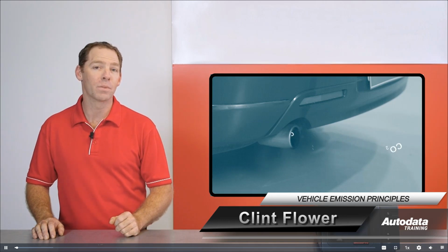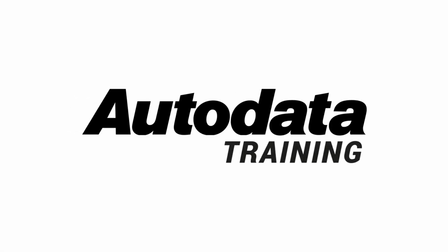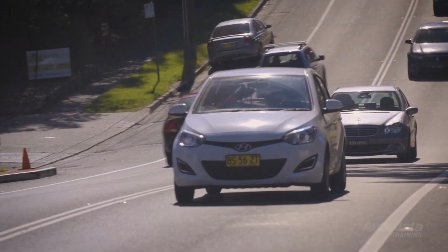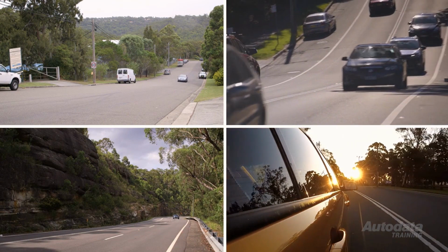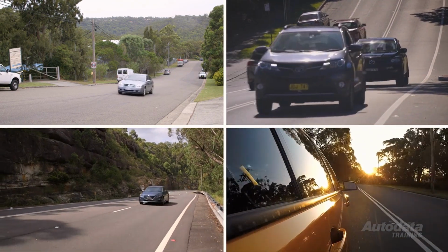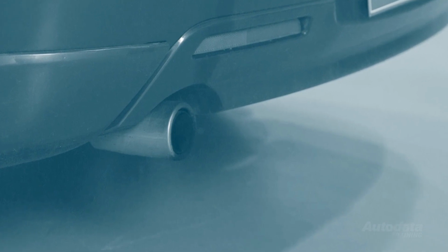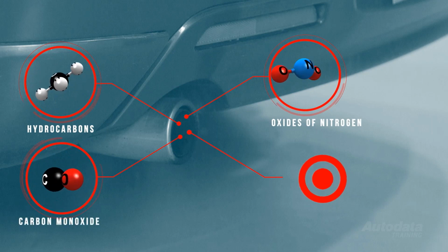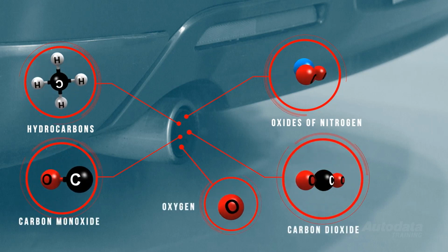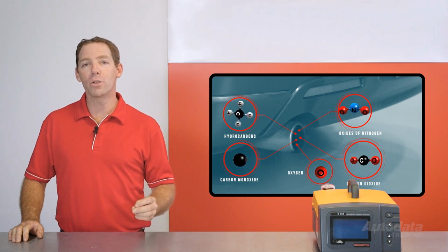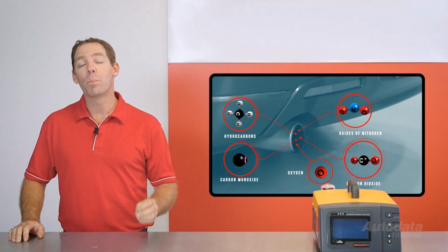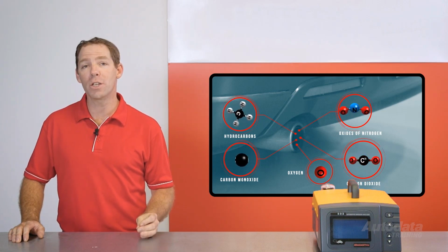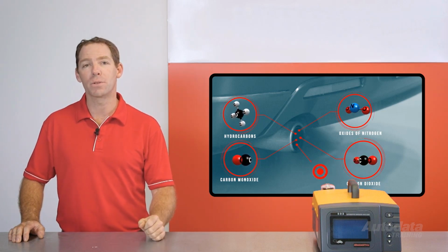of the engine management system. Or should I say, engine management is now a part of the emission control system. The drive for cleaner and more efficient vehicles on our roads has contributed to significant increases in drivability, power and reliability. Automotive emissions that are of great concern to technicians are hydrocarbons, oxides of nitrogen, carbon monoxide, carbon dioxide and oxygen. These emissions not only contribute to air and water pollution, but can be used to determine the operational efficiency of the vehicle's engine and associated systems.